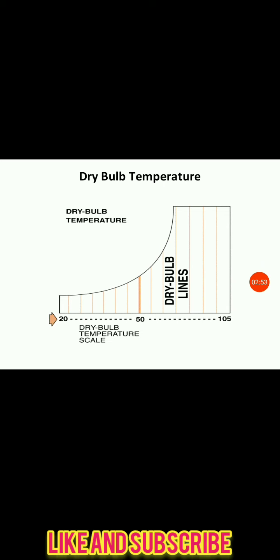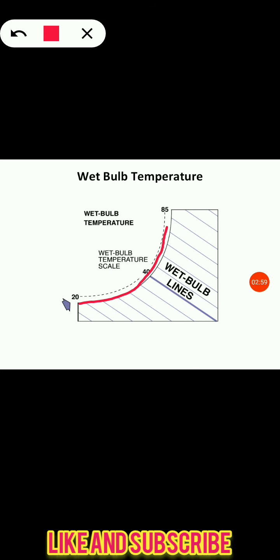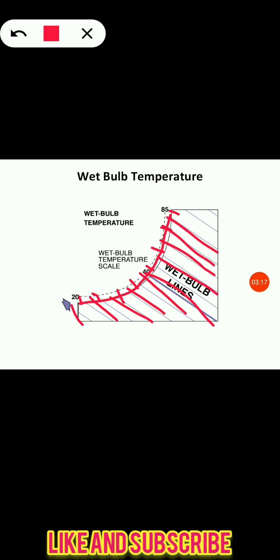Then next is the wet bulb temperature line. Here we can see a saturation curve. On the saturation curve, the temperature starts at 20 and goes on increasing along the saturation curve up to 85 degrees Celsius. These inclined lines indicate the wet bulb temperature of the air that is surrounding us. So inclined lines drawn on the psychrometric chart represent wet bulb temperature lines.